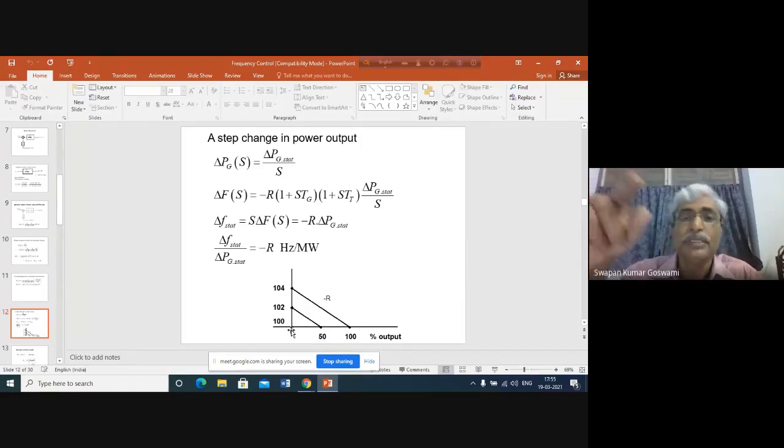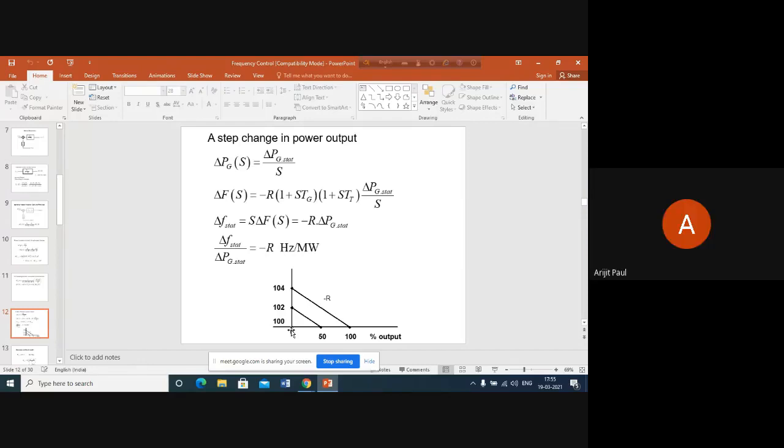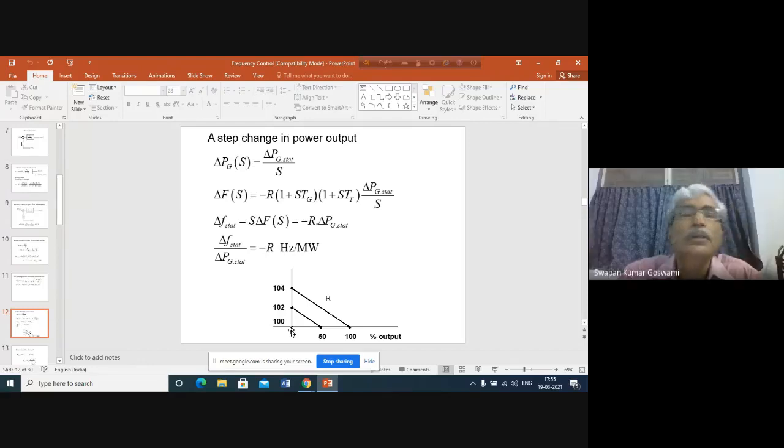Now you have a generator connected to a terminal load. So you need not maintain the synchronism here because you have only one generator. For the issue we are discussing here, you need not bother about the maintenance of synchronism, since you are increasing the load, the generator speed will be changing.